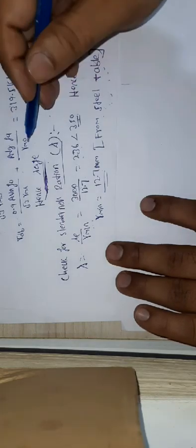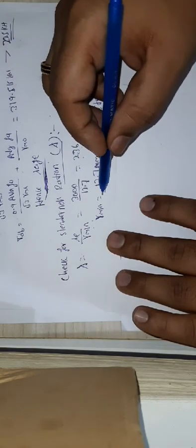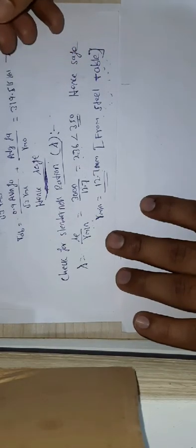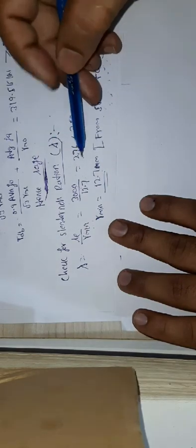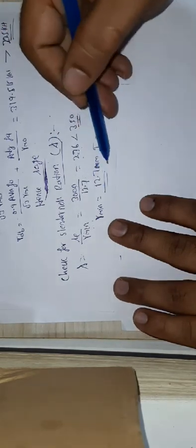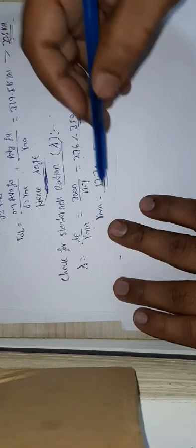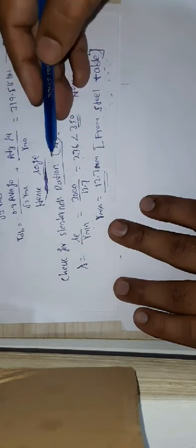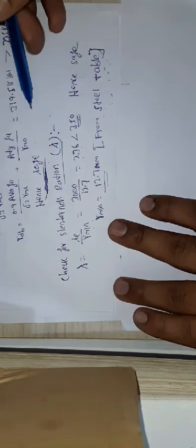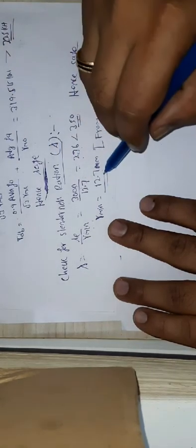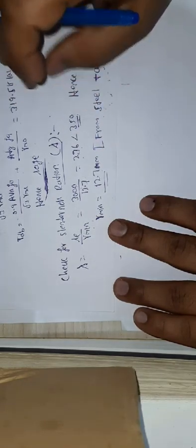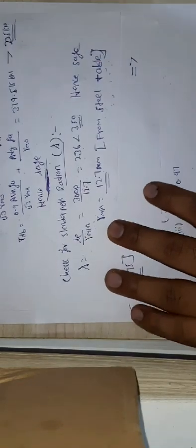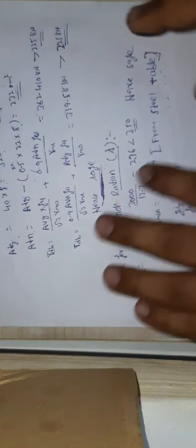Then where did I get the r minimum? We used to get it from the steel book. For given angle sections, we need to take the radius of gyration from the steel book. They give the value of r minimum there, and you need to take it from the steel book. So for the particular angle section, we need to take it from the steel book. Here for my selected angle section, r minimum is 12.7. That's how we need to check for the reversal of the stresses. This is how we need to do the problem. So now let us consider